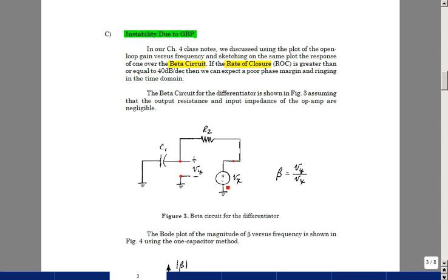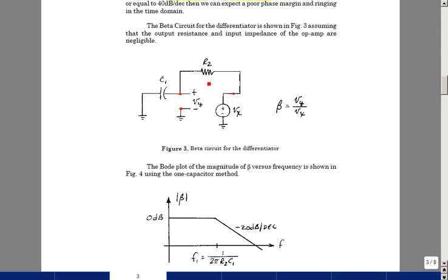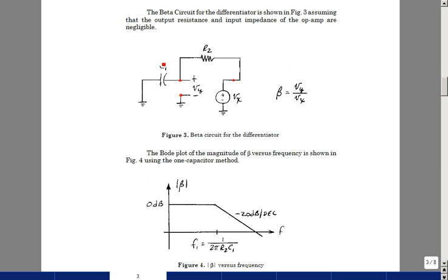So we can look at how this circuit is behaving and see if that's the cause of our stability problem, and it usually is, and then how you would fix or change it. Let's sketch what this looks like versus frequency. When the frequency is low enough, this capacitor becomes an open circuit, and no current flows.